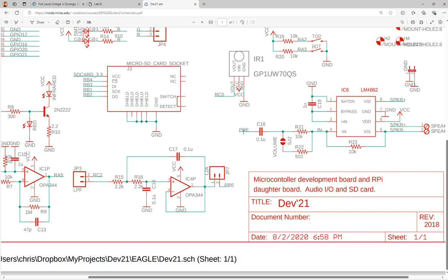And using the jumper here, because that's a schematic of the PCB, they are physically shorted already. They have the same name, even though they don't really have a trace here, but on the layout they are physically shorted. That's how the Eagle PCB schematic works. You just give them the same name, so when you convert to the layout, they will physically be shorted together. So these are already shorted together.